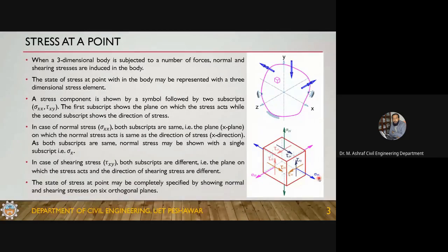The second subscript shows the direction of the stress, and you can see this is along the x-axis. So this is represented as sigma xx. Similarly, for this stress the first subscript is x because it acts on the x plane, and the second is y because it is acting in the y direction.